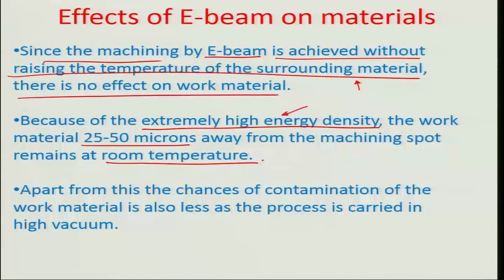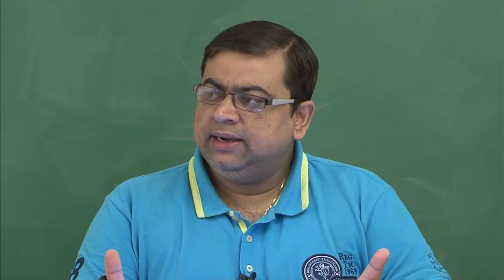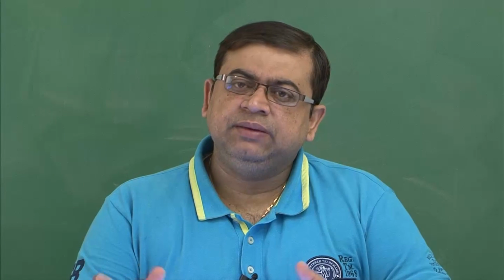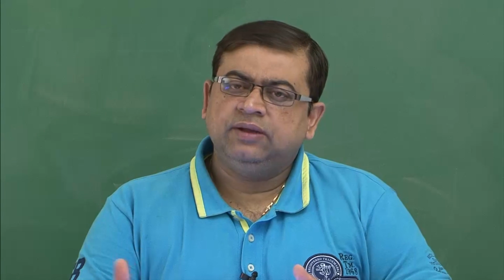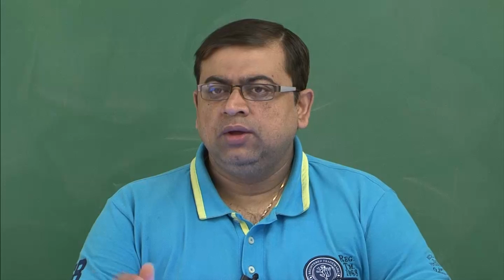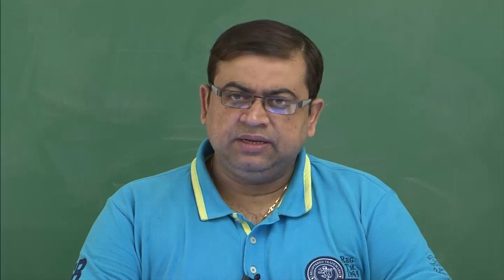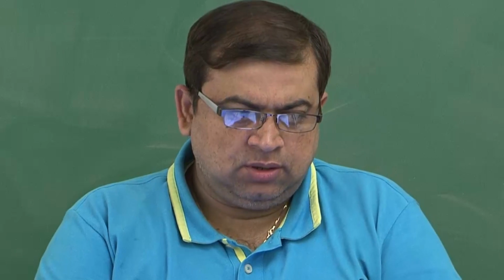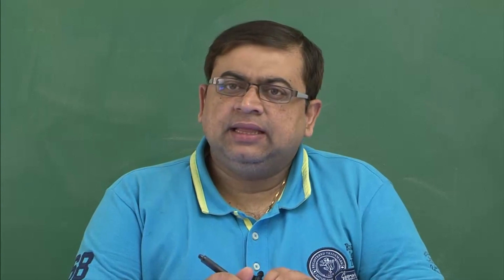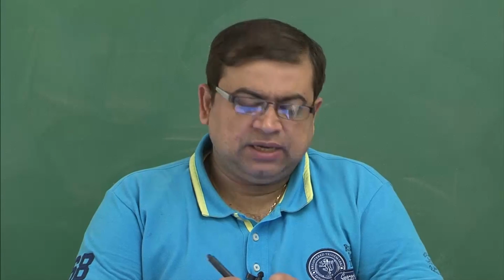The other issue for e-beam is that the chances of contamination of the work material are also very small, as, like I had earlier illustrated, the beam necessitates a vacuum column, and in normal atmosphere you cannot really have an e-beam. You have to have a pretty high vacuum level in the range of 10 to the power of -5 torr or so. Chances of contamination from the atmosphere are low, it is mostly a clean system, and even the handling is more or less with a load lock. So e-beam is preferable because of the less contamination and the less thermal damage to the remaining portion of the work material except the cutting zone.